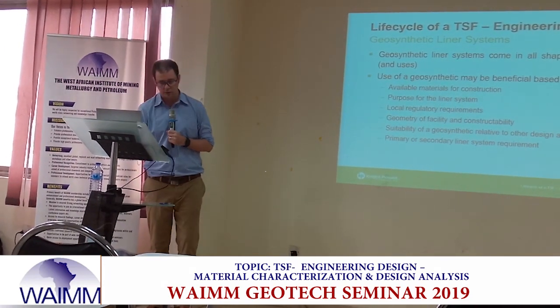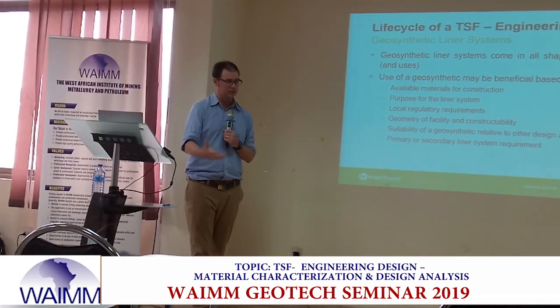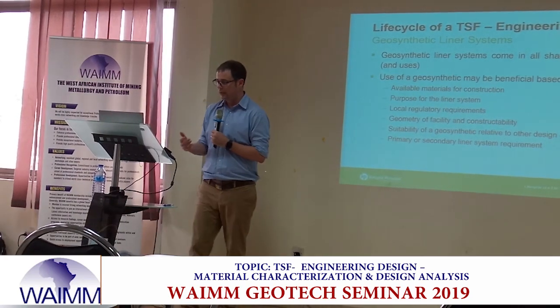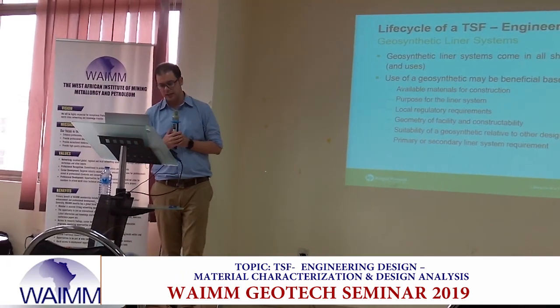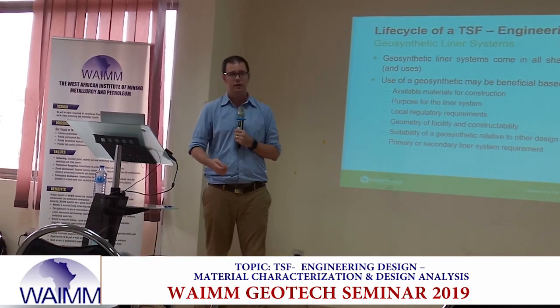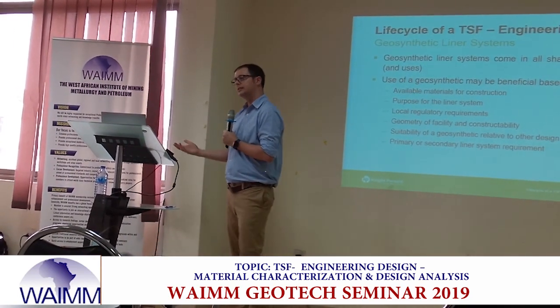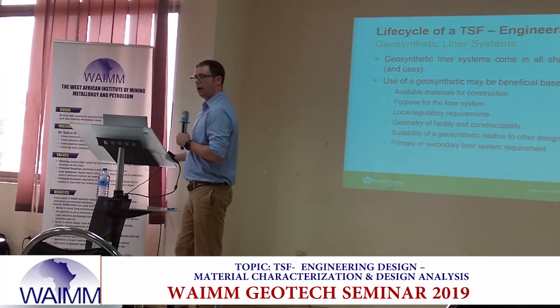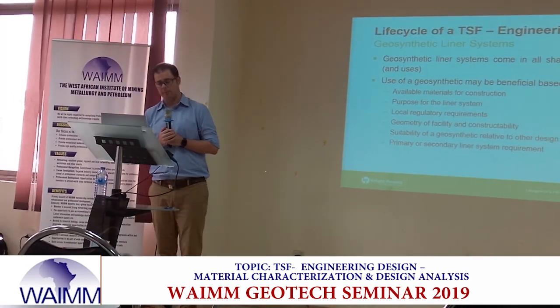Suitability of geosynthetics relative to other design aspects. We talked about some chemical interaction potential. And is a primary or secondary liner system required? Maybe a compacted soil liner is our primary liner, and we're using a geomembrane as a secondary liner. Okay? A belts and suspenders type approach.